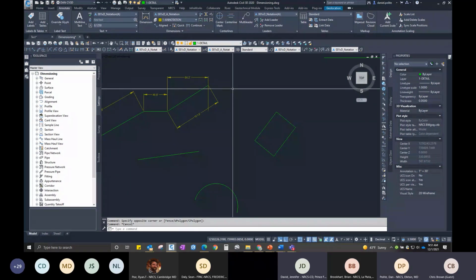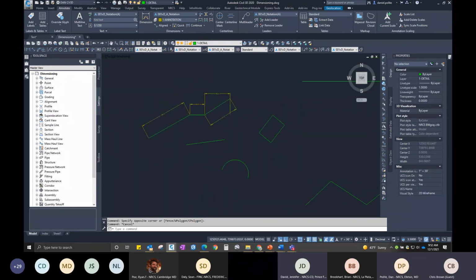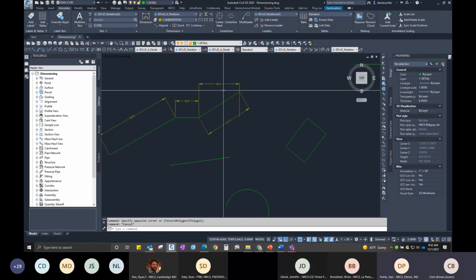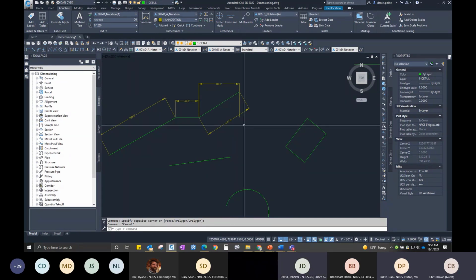So if you draw something that is 1 inch equals 40 foot in the vertical exaggeration, and 1 inch equals 20 foot in the horizontal, if you dimension horizontally from the point where the pipe starts to the end, that will be a true distance, even if it's on an angle, if it's got some type of slope to it. Yeah, I understood what you meant. I just wanted to make it clear for everybody. Yeah. But in the 2D world, it will change. Yep. Thank you.